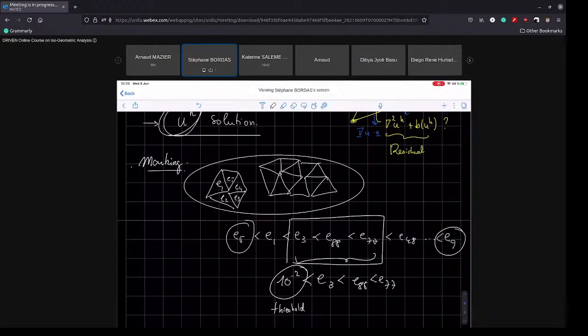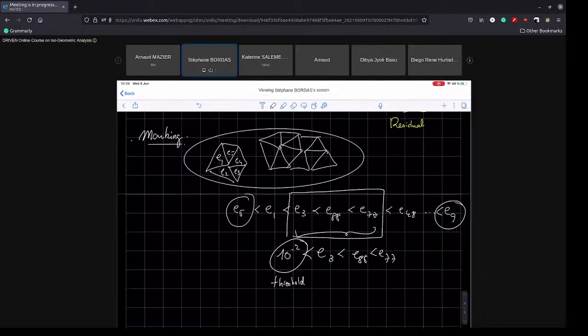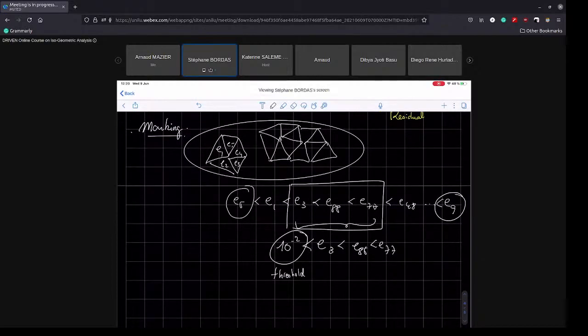And once you have done that, you refine the mesh, and that is done either by mesh refinement or by moving the nodes. It's called R adaptivity, like relocation adaptivity, like when you move house. All these nodes actually move houses and move around, but you don't change the number of nodes. You just relocate them. Or you can use edge bisection, when you split the elements into two. So that's the basic idea behind this. Or you can use P refinement and say, okay, I don't like what I'm seeing, so I'm going to increase P and see what happens.